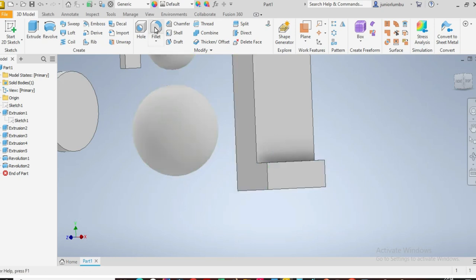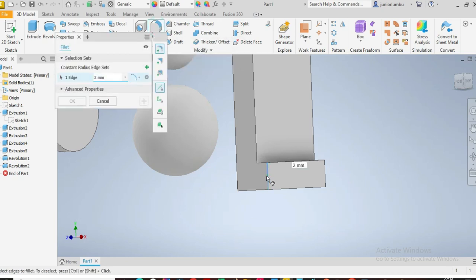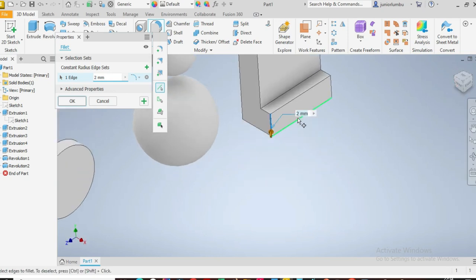You don't have to click on there, but you can also click on there, and then you come here, and then it will ask you what radius you want your fillet to have. So you can choose, for example, I can say 10mm radius, then there comes your fillet. Again, you can go for 25mm radius, then comes your fillet.